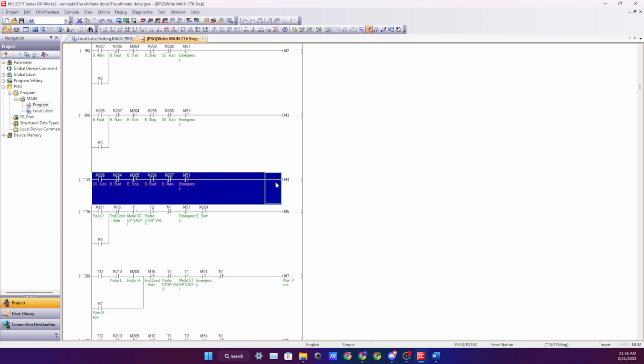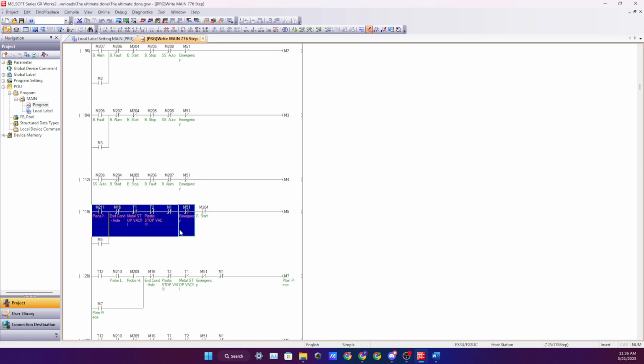All the way down here, this one is the sensor that checks for the piece, and it will be cut by the end condition when M16 activates. The sequence, which we will talk about below, cuts the condition which ends the routine of one loop.